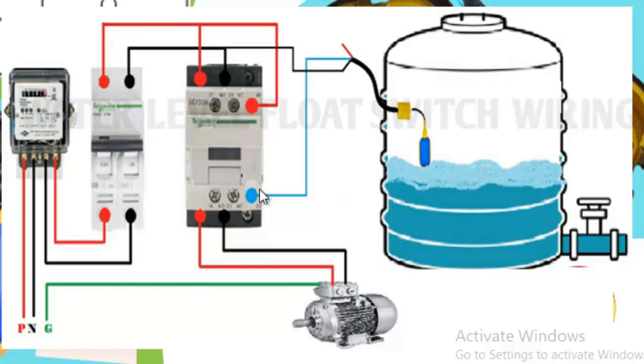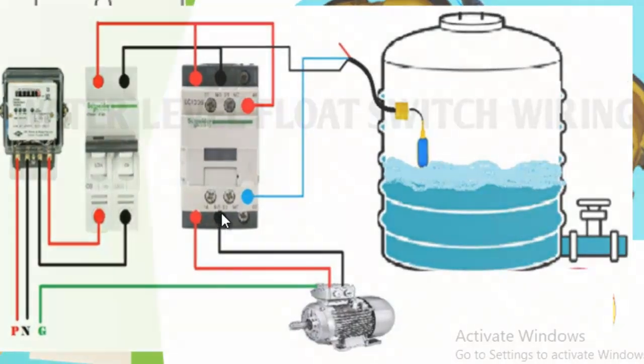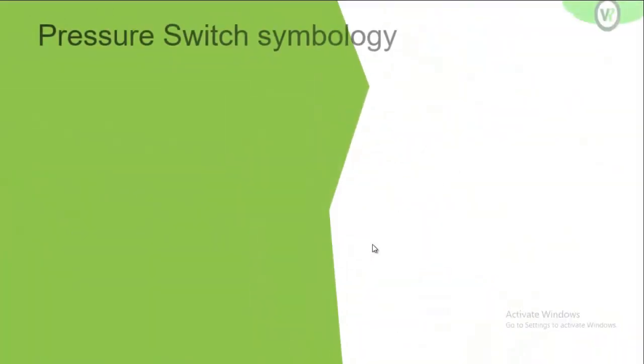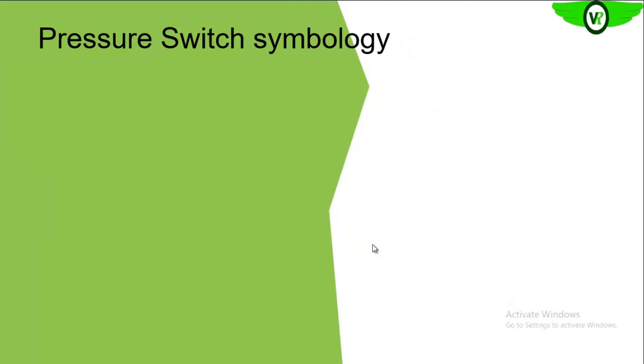The ball will now roll off that arm as earlier depicted, and once it rolls off that arm, the switch will be deactivated, and then the pump motor will stop, because the contactor coil will now have power broken to it, it will drop, it will be deactivated, and then the motor will stop. So that is how the float switch is connected.